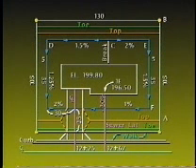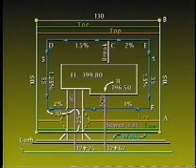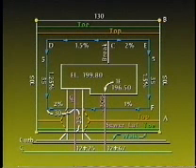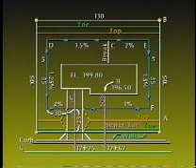The elevation of the flow line at point D can be computed from the grades and dimensions given on the plan. Finding the distance from the swale grade break in the driveway to point F at the flow line of the swale is a bit tricky. Here is where you can use your years of experience poring over architects' plans that always seem to omit key dimensions. The dimension from the west property line to the center of the swale at the center of the drive can be calculated and is 35 feet.